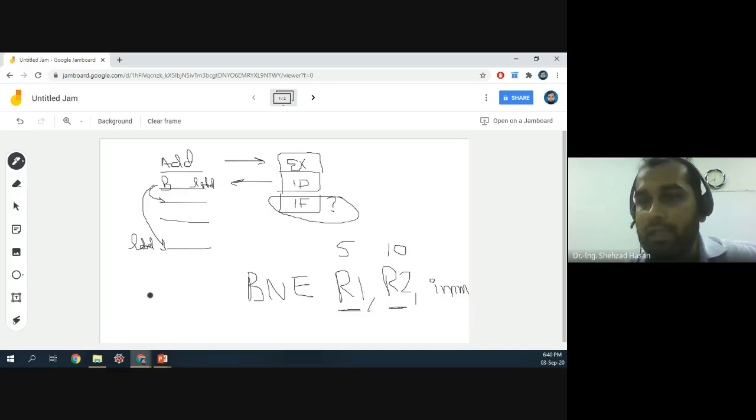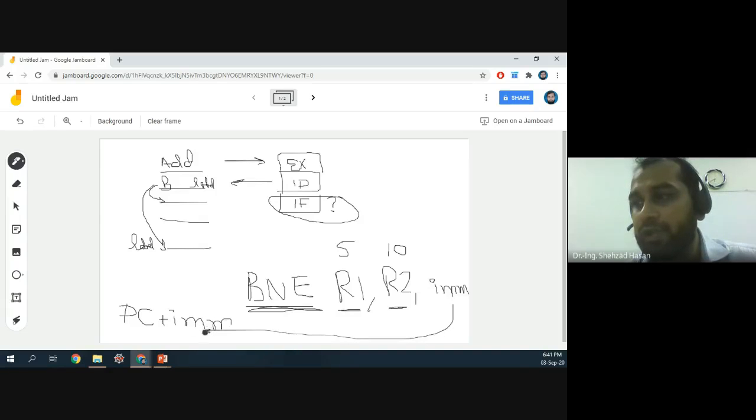In simple processors or RISC-based processors, you don't have many addressing modes. For branches, you have a very common addressing mode, which is called a PC-relative jump. All of these jumps are relative to the program counter's position, so every jump is relative to the current location of the branch. We add this immediate value to the current program counter value.